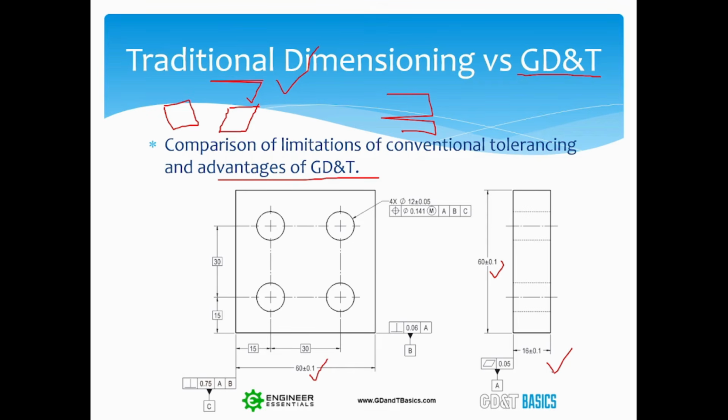That's why I give the geometric dimensioning also. First I have put A as a datum, and I propose that these two faces are parallel within a range of 0.05 mm. Then this A becomes the datum for the condition that this face B is perpendicular within the range of 0.067.